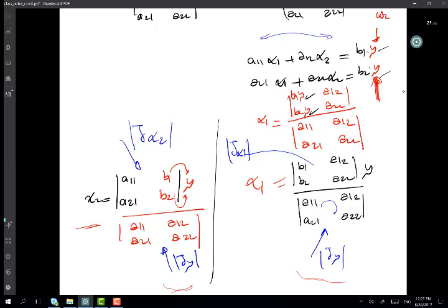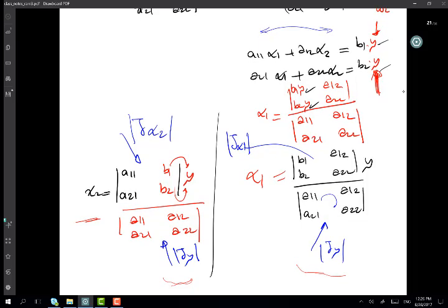And this means if y is equal to 0, y is a velocity in our calculation. So this means the link has stopped, right? But if the link is not going to stop, if our intention is that this link will keep running for continuous rotation, then if y is equal to 0, it's a disaster, because the linkage will cease or break, because now the system will disintegrate and cannot be a physical system anymore, right?